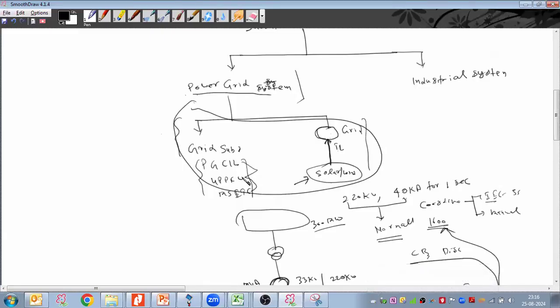So when working with the grid, you will directly go with the grid short circuit current. When working with the solar, first go with the grid short circuit current. But sometimes in the calculations, if taking the grid short circuit current, you are not able to meet it, or the calculated knee point voltage of the CT and earthing is not met, and is coming very high, then re-modify and take the actual short circuit current which is injected by the grid to your end.